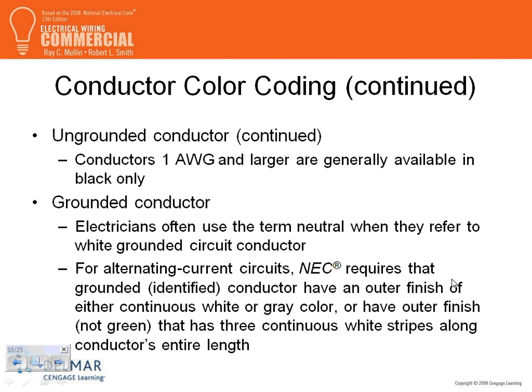So in a situation where you might run into a gray conductor as a service entrance or whatever, what other color would you use? If you continue from a switchgear where phase A is gray, existing, and you will add to it. I have not run into that. But what if you ran into it and you don't want to replace it, if the gray is used as phase A, you don't want to use a gray as a neutral. So you might have to use a white, or something else other than neutral.